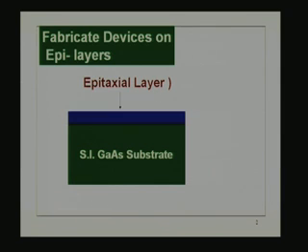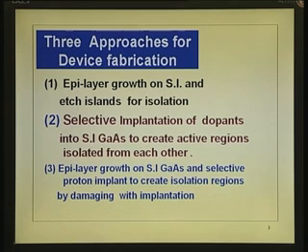For example, in the case of silicon integrated circuit, very popular technique is p-n junction isolation, but when you want high performance, there also you go for semi insulating substrates. So, now let us see what are the methods which are used for isolation in gallium arsenide based mainly.